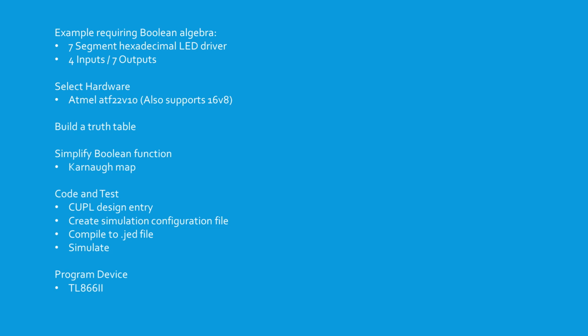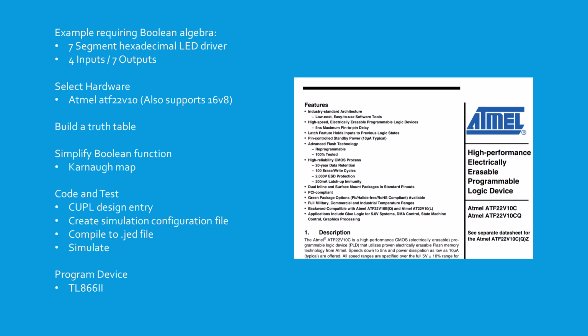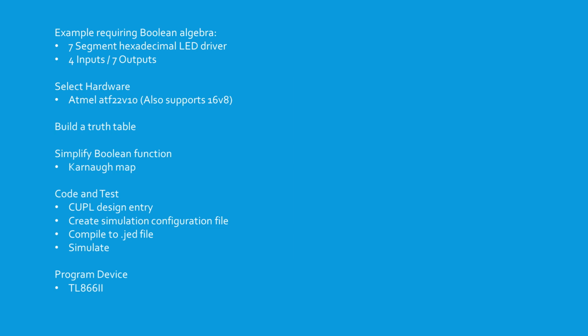For the specific hardware, I will be using the Atmel ATF22V10 PLD, chosen primarily because I have two in my inventory. There is a smaller pin count IC, the 16V8, that would have used less real estate, but the project is for my own learning and reduced pin count was not required.